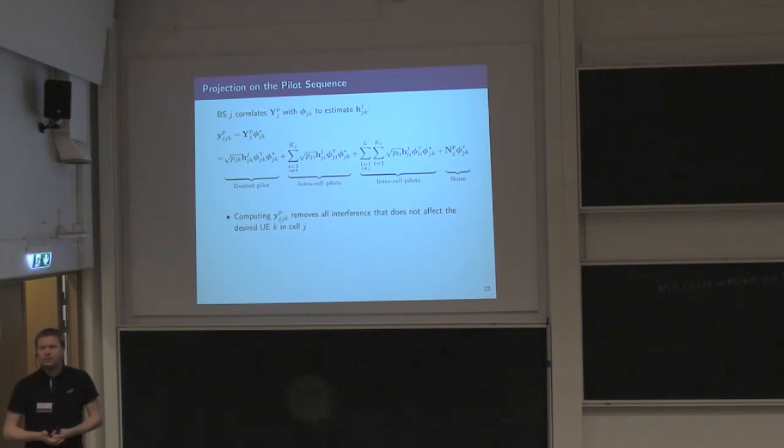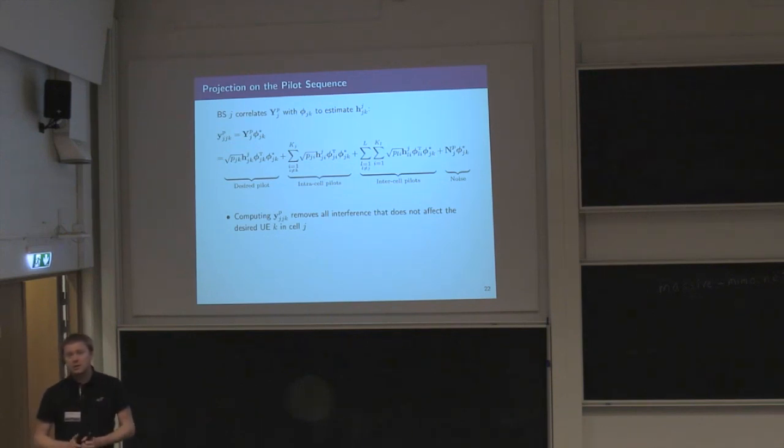Are you assuming that the whole network is synchronized? Yes, we have assumed that the whole system is synchronized. In practice, you can make sure that your cell and the neighboring cells are sufficiently synchronized. For example, in an OFDM system, all of the variations that are within the cyclic prefix, or the distance of that, which is like 2, 3, 4 kilometers, depending on which length of the cyclic prefix you're using, those will easily be synchronized. But further away, things will definitely never be synchronized perfectly. That is something that we assume here to keep the math simple.